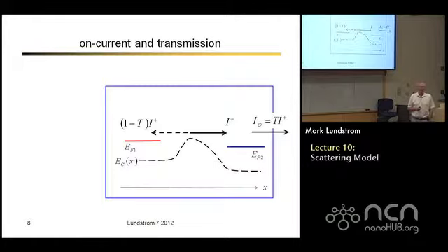What that means in practice, oh, we're finally getting some rain. What that means in practice is that in order to get the charge that we need, which MOS electrostatics says is always Cox times (Vg minus Vt), that's never going to change, we can now inject less positive flux, because we're going to get some negative flux too. And we'll add the two together. So we won't be injecting the same flux that we did in the ballistic case. Let's see how that works.